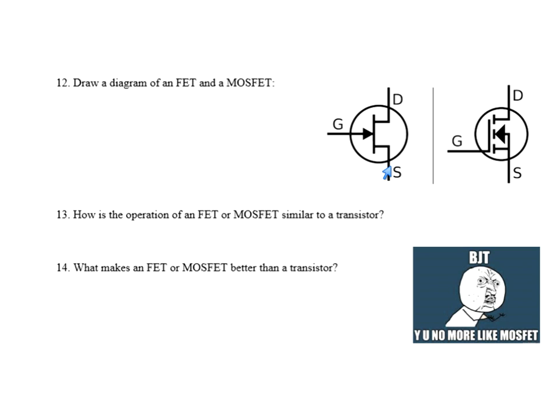So anyhow, the basic idea behind it is there's a lot of current in the drain and the source. And by putting a higher voltage on the gate, I can shut that current off. Higher voltages on the gate shut this off in here. Lower voltages on the gate turn it on.